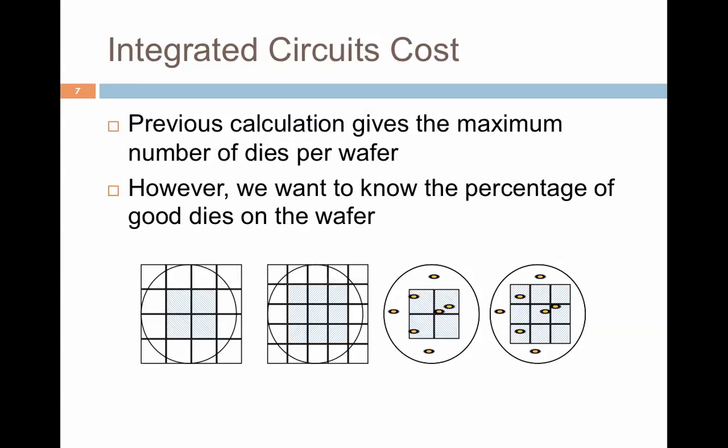Then when you go into the higher layers, the next set of layers are called intermediate layers. So the bottom layers are the local layers, the middle layers are the intermediate layers, and the top layers are the global wires or the global layers. The intermediate layers are mostly for networking. It is used to connect different routers or different crossbars. And the top layers are mostly for power distribution. So you have a power system which drives various components, and they are all at the top layer.